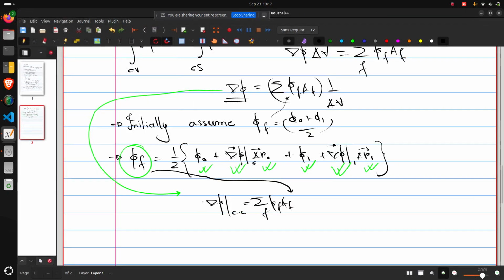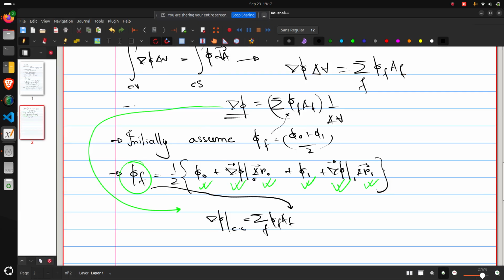So it's quite simple, I guess. First we get an approximate gradient of phi, then we use this value to compute the phase center phi values, and with those new phase center phi values we again get another approximation for the gradient of phi. We just do 2 or 3 iterations like this, and we'll get a quite converged result.